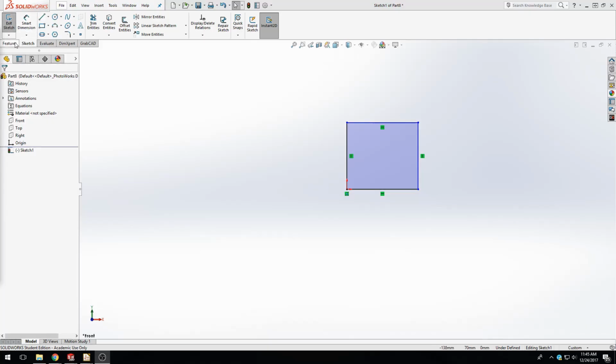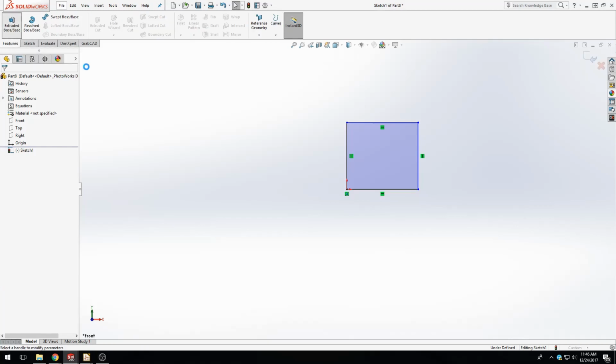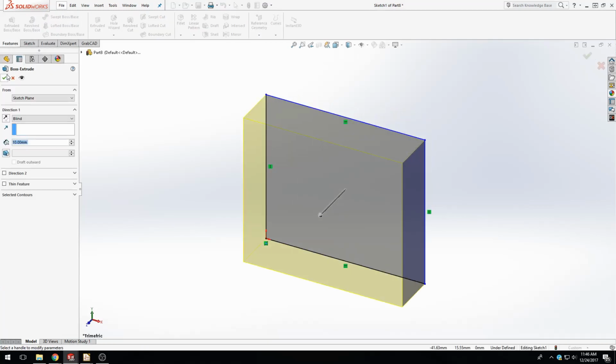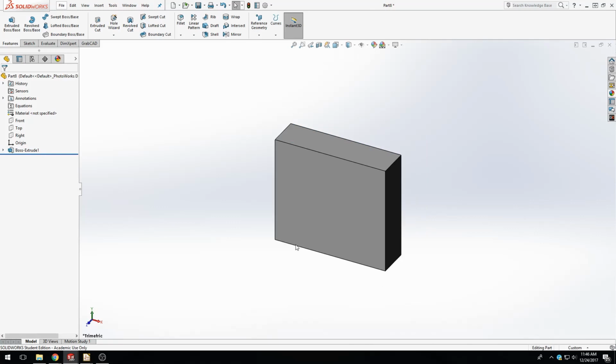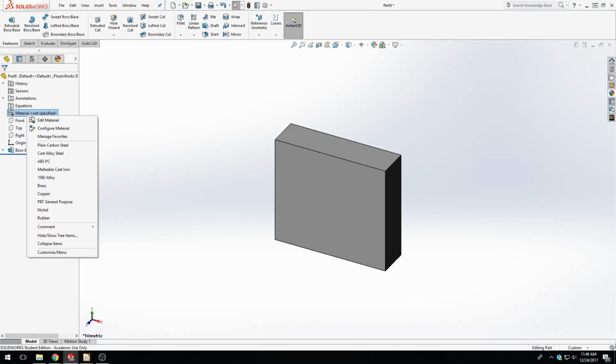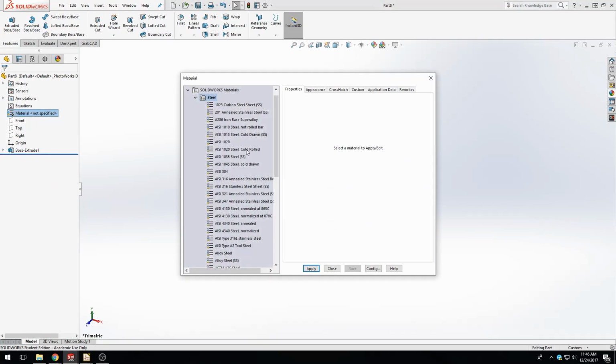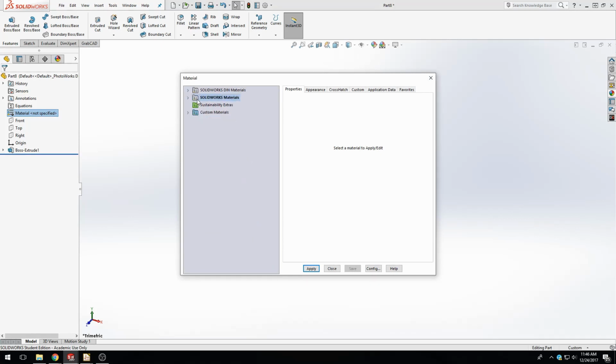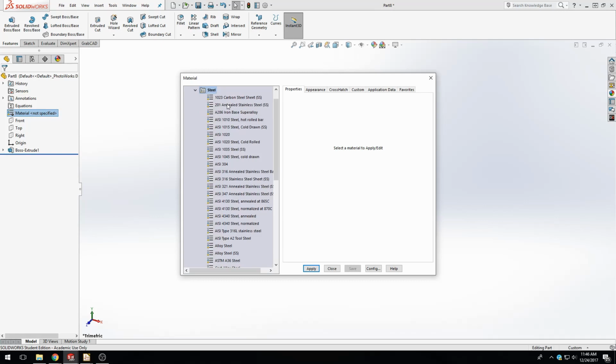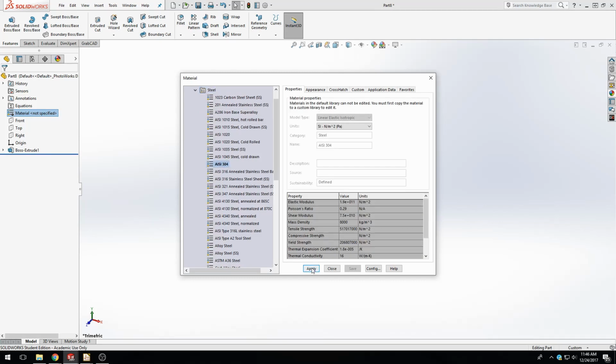For a SolidWorks exam, how you enter your answers is you enter the mass of the part that you've made. So, if say this is our part, to add mass what we want to do is we want to first add a material. So we go right here, edit material, and then it'll give you a material that it wants. It'll always tell you exactly what material it is. So say our material is this, or whatever. It'll also give you the density, so it's a good idea to make sure that the density of the material you're using is right. So if it'll specify like 8,000, this is 8,000, we're good to go.